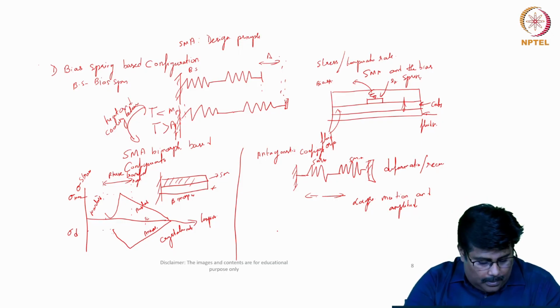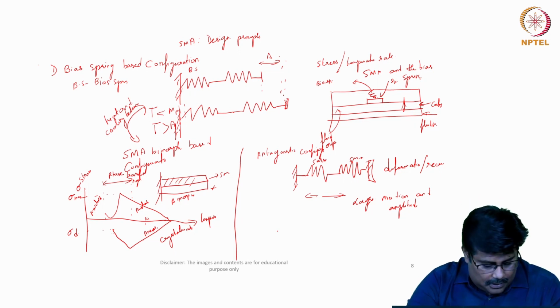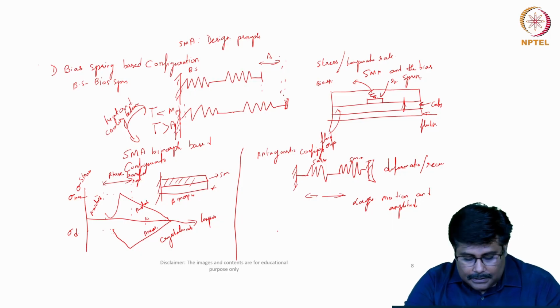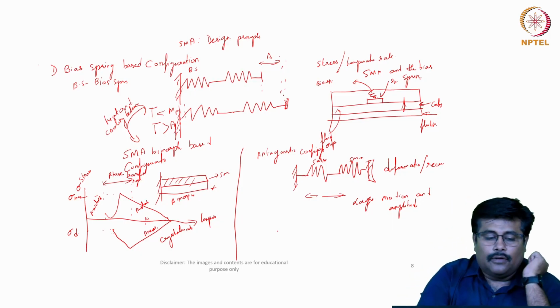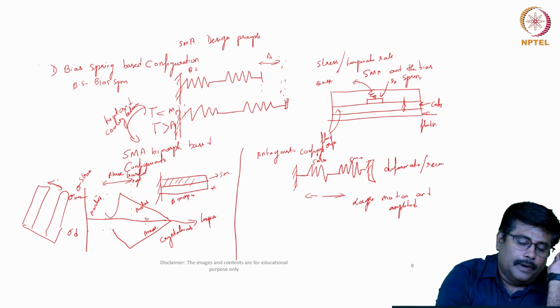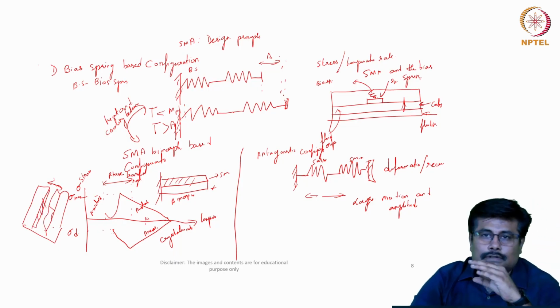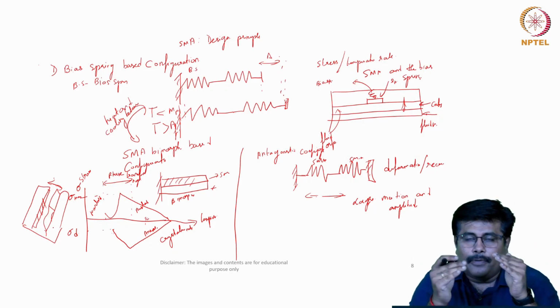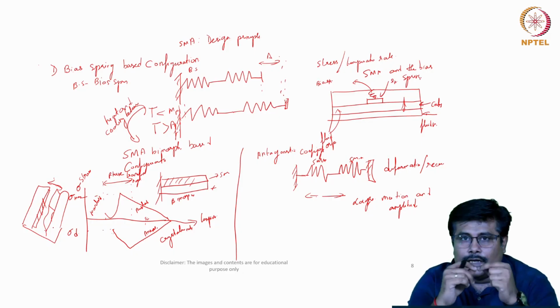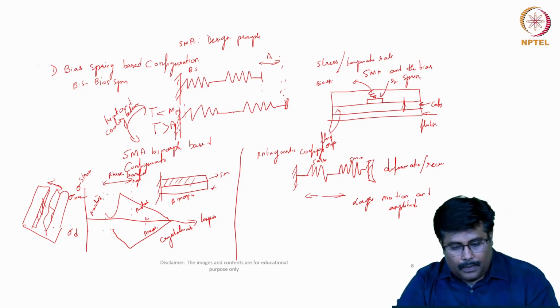So in the device operating mode, the biasing stress can be effectively used to deflect, for instance, an Si cantilever beam or a membrane. Like this can be used for a kind of a micro gripper arrangement. For example, if this is a micro gripper arrangement, and here we have a bimorph kind of structure, we can give a biasing appropriately to get the required actuation.